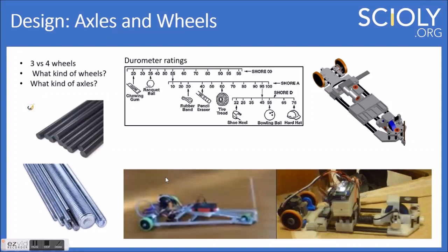So the advantage with the softer wheels comes when you have a lighter device and you need more grip. If you're going to have a smaller normal force, just because the mass of the device is smaller, you're going to need a higher frictional coefficient to compensate for that. But once your device starts getting heavier, if you all of a sudden brake suddenly with say the 30A wheels, you're going to start really degrading them very fast, and they're going to lose their quality, and you're going to see these little rubber pieces falling off of them. So that means you might want to switch to a less soft wheel, which would be the 40A or the 50A. So it kind of depends on the mass, I would say.